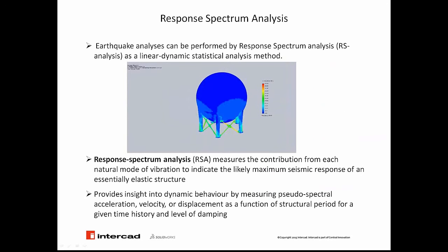Okay, now let's have a closer look at the response spectrum analysis. Earthquake analysis can be performed by response spectrum analysis, or RS analysis, which is a linear dynamic, statistical analysis method. You can see in the picture that we have a base excitation, and we would like to measure the contribution from each natural mode of vibration and see the structural seismic response to such a base excitation.